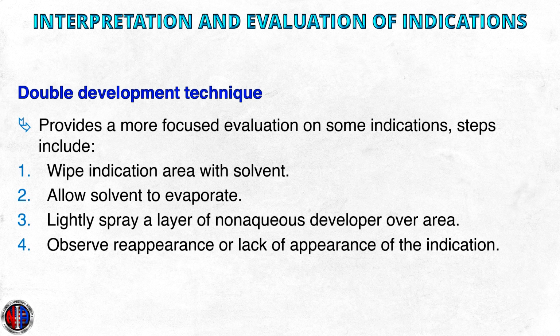At the conclusion of the evaluation phase of the inspection step, further judgment must be made concerning the disposition of the test object by evaluating it against established acceptance and rejection criteria. NDT procedures specify the acceptance or rejection criteria, as well as supplemental documents such as applicable acceptance-rejection specifications. If liquid penetrant tests are being made on critical parts such as nuclear hardware or jet engine components, an industry expert in indication evaluation may have to be called upon.